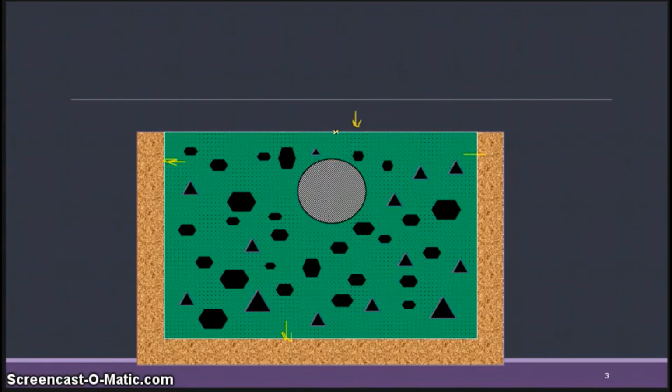Now why is it going to subside? You have water in the system. Due to vibration or due to the segregation, the latence comes up on the top. That latence contains a lot of water; majorly it is a mixture of cement and water. Also, there's a layer of water that can come up, which is called bleeding.